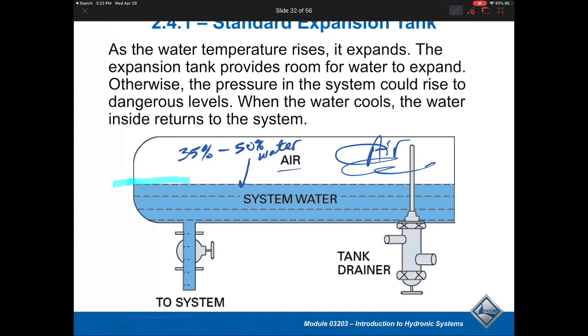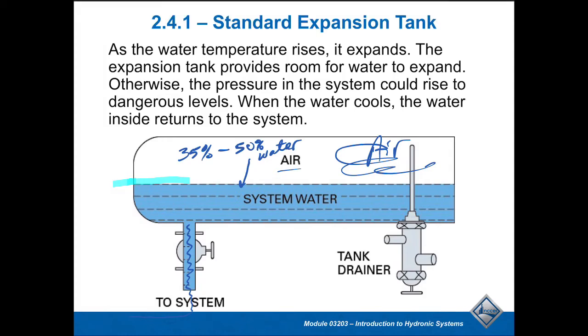Typically on a lot of the older systems, this also was our air separator. So a lot of these older systems, we would have expected a lot of those little bubbles to make their way up into the boiler system, and that would have acted as an air separator. There's a downside of this.